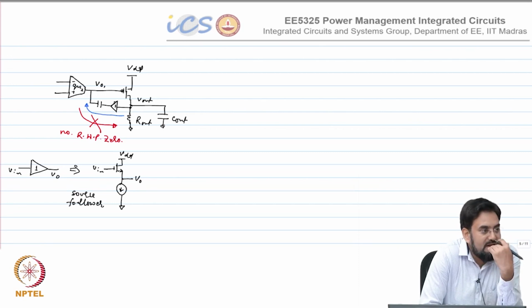And what will happen to the Miller cap? In this case, your Miller cap is the output stage gain, GM R out. Now you have one more gain stage in that Miller loop, so GM R out is multiplied by that A times. So your Miller cap will also get boosted. So that's the advantage if, instead of a buffer, you put an amplifier in the feedback. Then you can push your output pole to higher frequency and the dominant pole even lower, which means that will require a smaller cap because your multiplication factor is now increased.